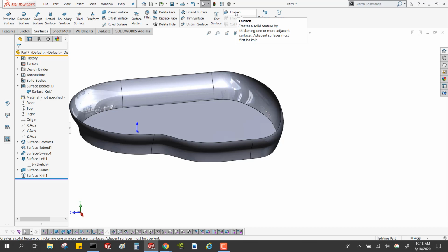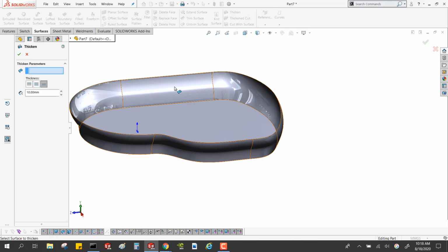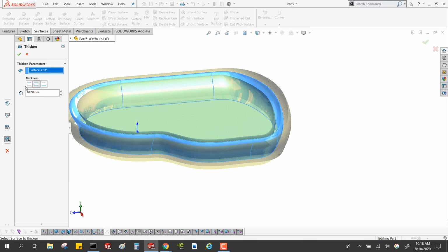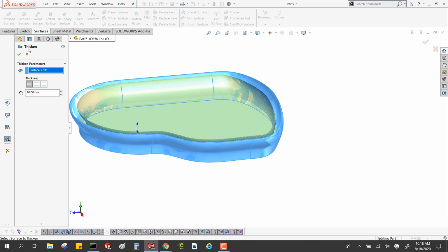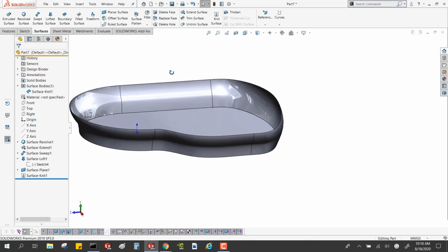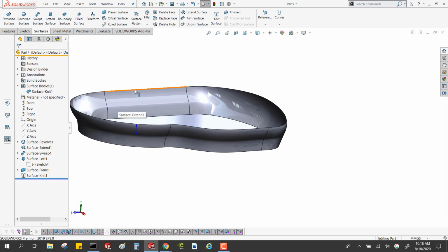I was talking about why do you want to use surfaces in solid geometry? Well, sometimes you have a particular surface that you're trying to capture, like the outside surface of this shape. I can do it with surfaces, and then once I've got my shape, I can choose to thicken that mid-plane, inside, outside, make myself a bowl, turn it into a solid that way. Or if you do have an enclosed volume, you can make it into a solid.